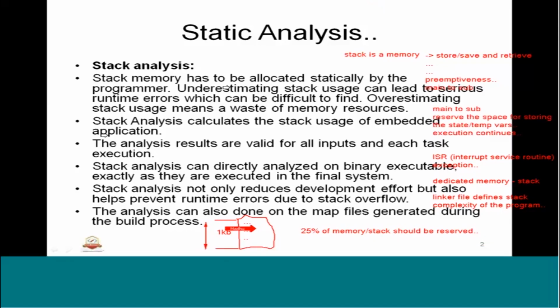Okay. So we should not overestimate, and we should not go overrunning the stack. That is very important. The stack analysis calculates the stack usage of the embedded application. The analysis results are valid for all inputs and each task execution. Definitely, for each task we should know how much stack it is going to use. So the results will validate all this.